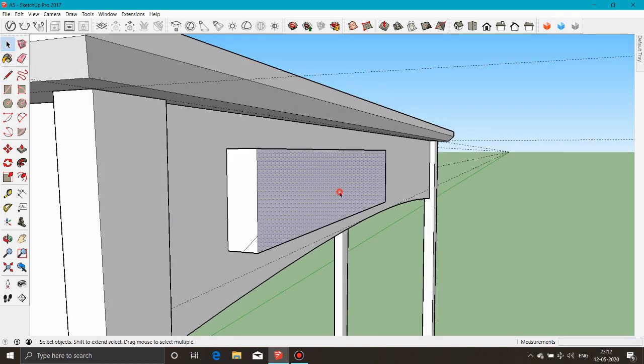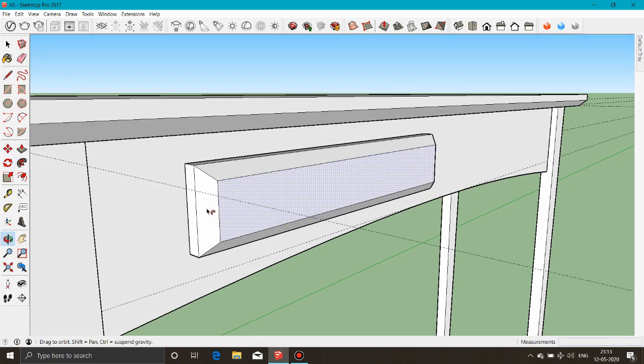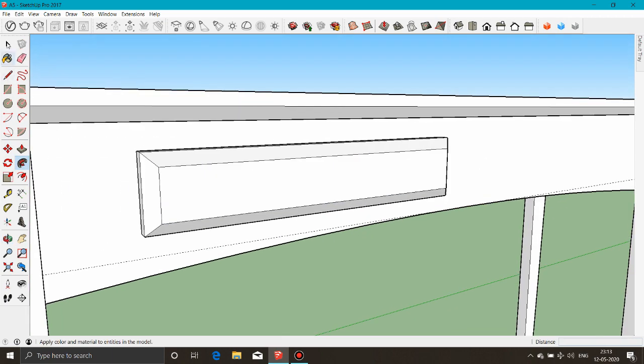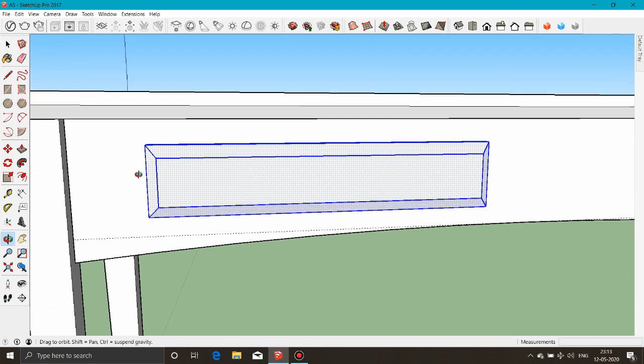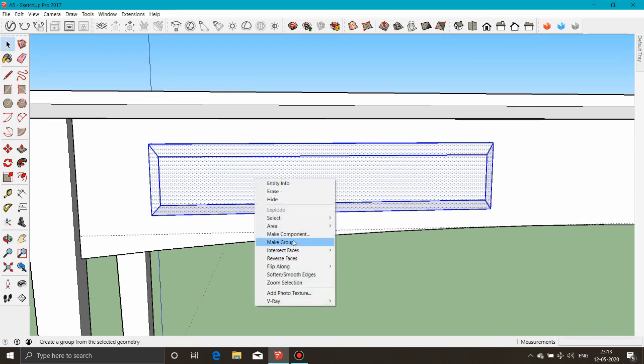Now you can use push-pull on the arc. Push it until it meets the back surface, which will delete it. Close the component. We won't create all the internal elements or drawers that a real table will have, but let's finish this example by creating the drawer fronts so our table looks complete.